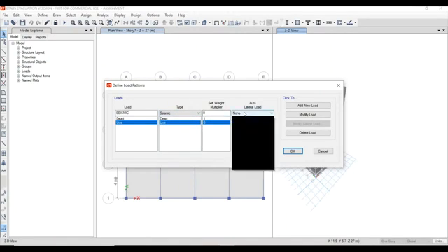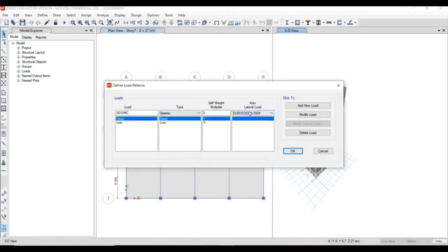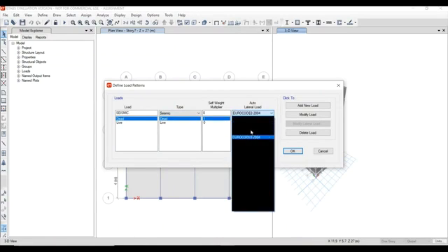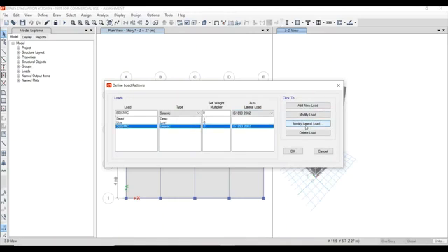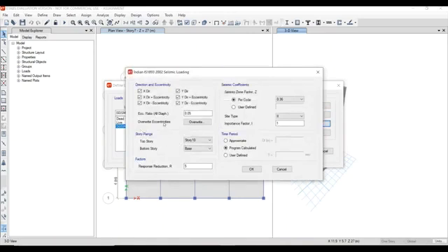Now auto lateral load. Sorry, there is a small problem. Let us select the auto load from here. IS 1893 2000. Select IS 1893 2002. Add new load and modify the lateral load. In seismic load, we will be having IS 1893 code.